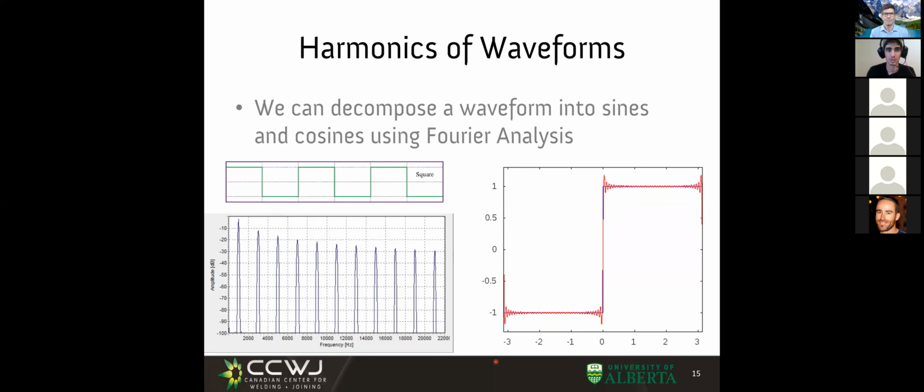Now, let me tell you, do you think you can do AC TIG with long wires, with long leads? Of course not. The answer is that if we have long leads, we're gonna turn our square waveform into a sine waveform. Now, if you don't know any of these things, you think it's just magic in action. Why one yes, one no? They have a cable, everything of the connection is good. But we understand, and we can make sense out of all these things.